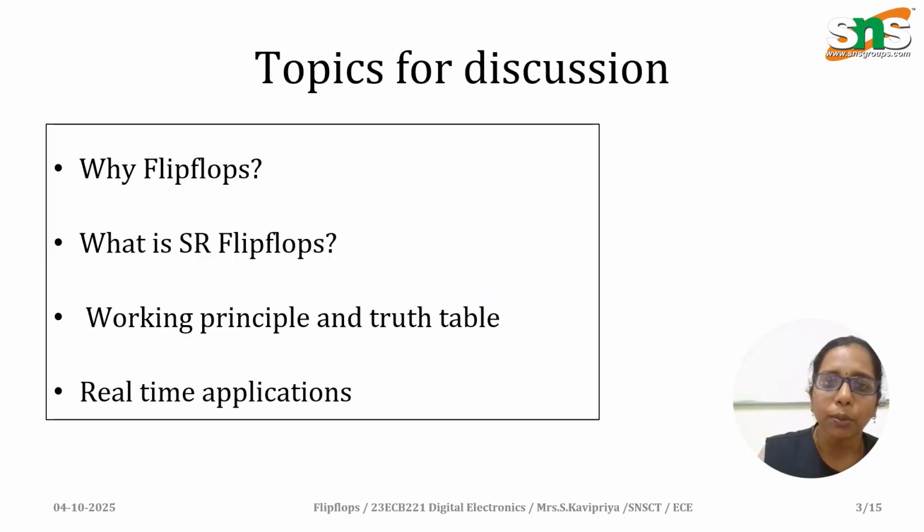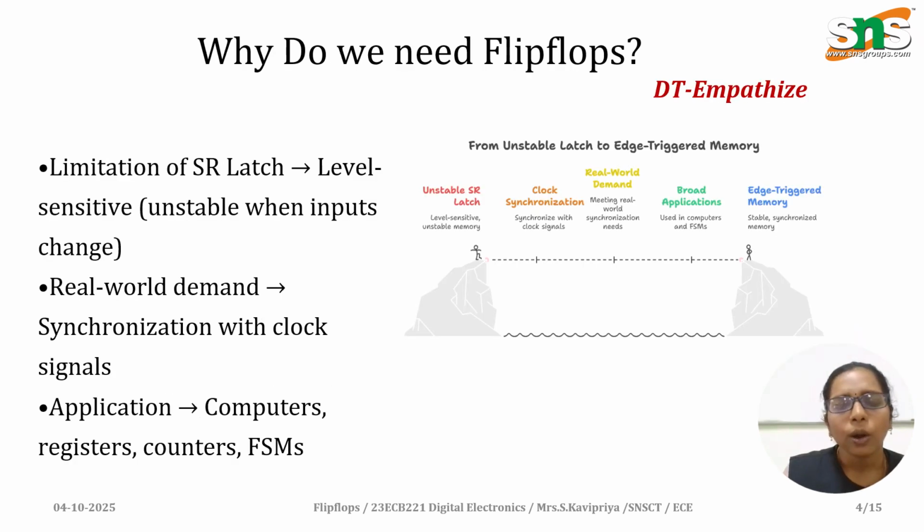I'm going to discuss why flip-flops are required, what an SR flip-flop is, its working principle, truth table and characteristic equation, and finally the real-time applications of flip-flops. Why do we need flip-flops? As I discussed earlier, the main drawbacks of latches are that they are not synchronized with the common clock pulse, and they are level sensitive and highly susceptible to noise.